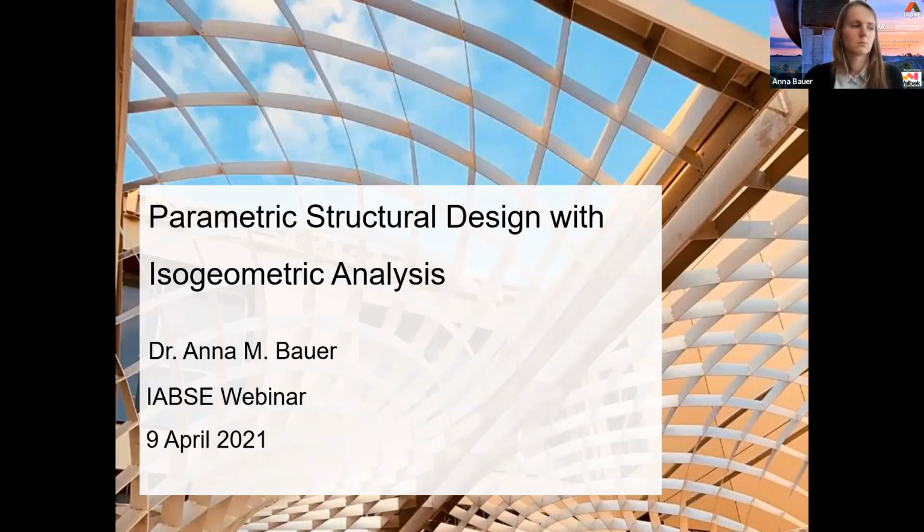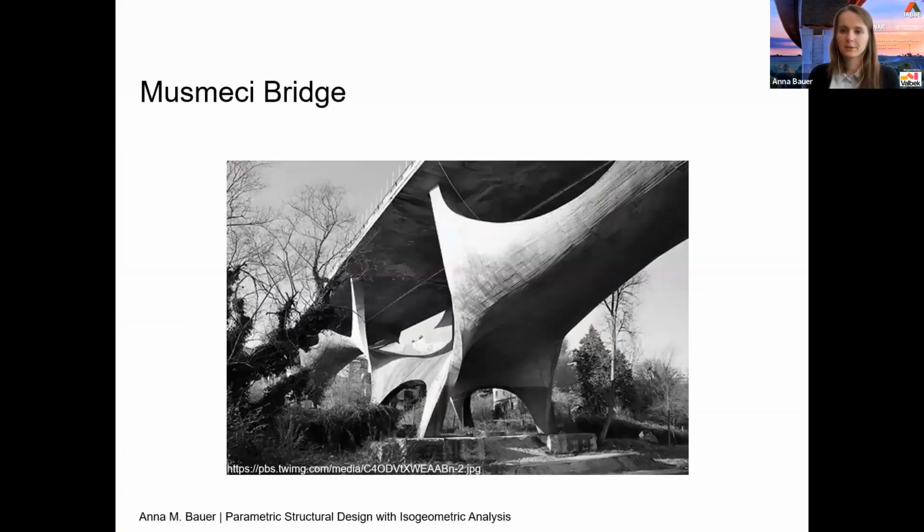This bridge here in Italy is a really good example of what we were looking for. It's a non-standard bridge, and somewhat complicated. It's not possible to just draw it and then do the calculations. The shape of the support construction is chosen such that it has a good utilization. It is mainly loaded by normal forces, so a membrane shape is adapted for this concrete bridge.